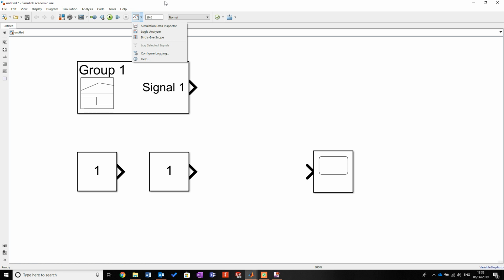The trouble is, if I put in a variable that's out by a unit, so let's say I wanted 1 mil but accidentally put 10 mil in, the system will still execute. And if it runs, a lot of the time you can't visit the data, you can't be sure about what's happening. Now the Simulation Data Inspector, if there's one thing in particular where you think, if I can see that, I will know if that's going on, yes or no, you can have that live updating, checking it.